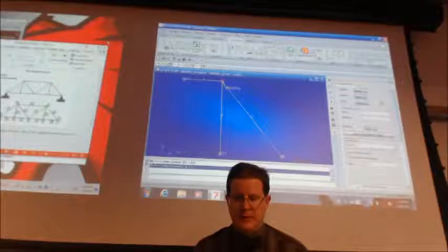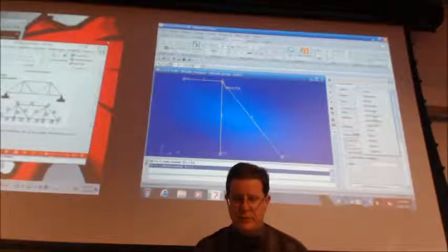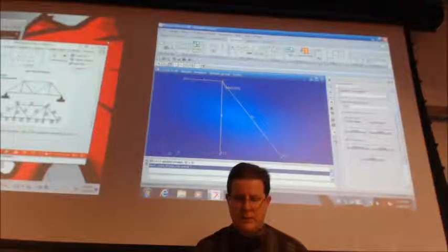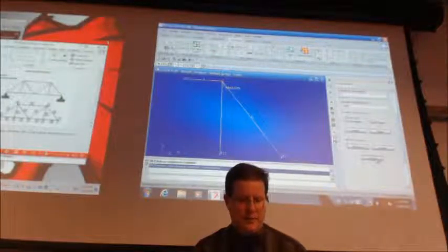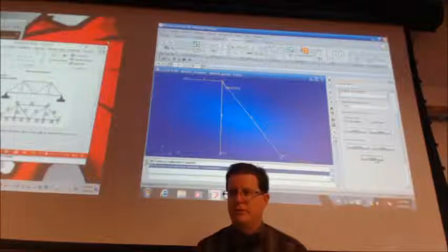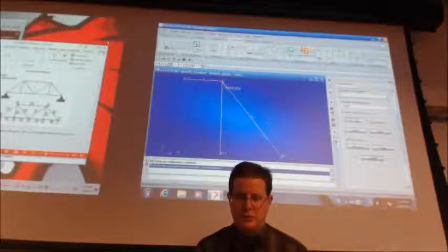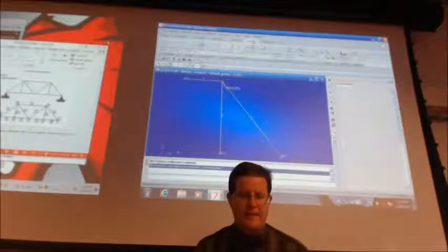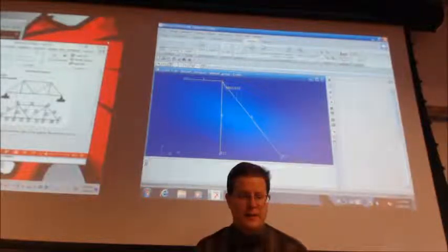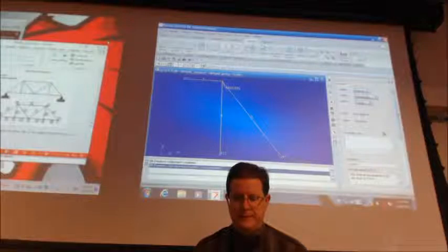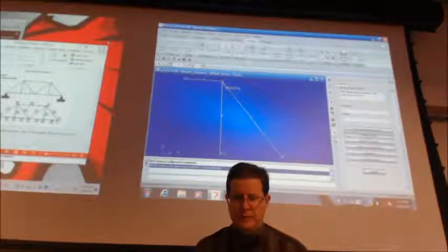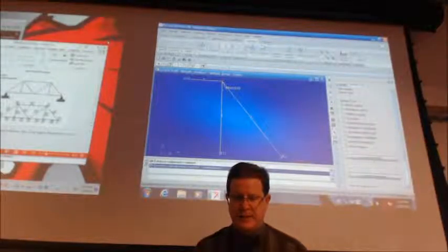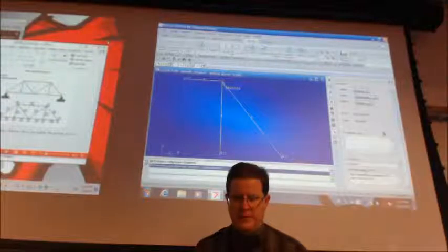Okay, and then while I'm here, the other thing we have to remember to do is go in and do equivalency and apply. And I got rid of 2 superfluous nodes, just one on top of the other is all that is. So now we can tell it to analyze the entire model. Make sure our solution type is linear static. Okay. And then job name.